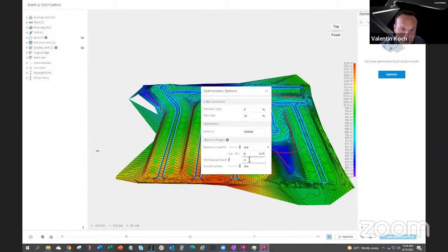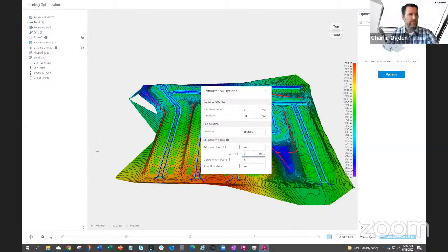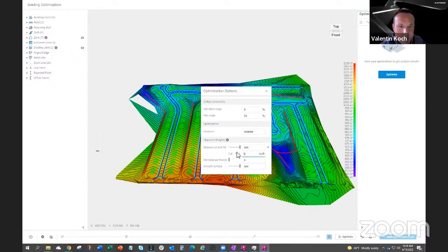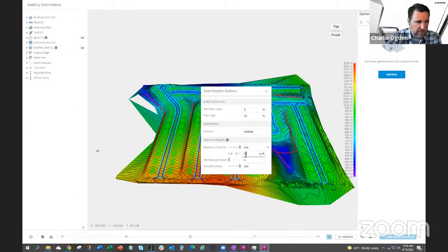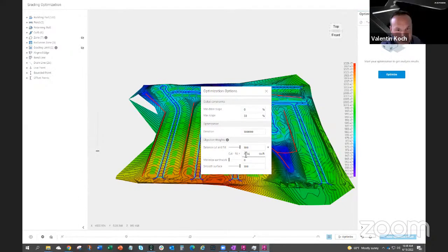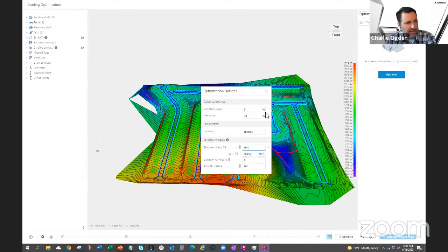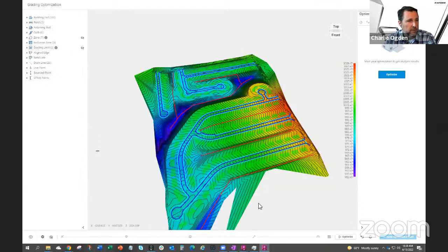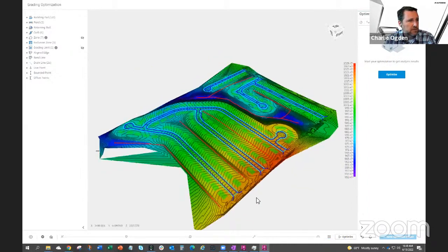So it was a fill. Is that right? Yeah, it was a fill. So we want a cut value. We want a positive one in here because this is cut minus fill, right? Yep. So what was the number again? 70,543. Perfect. So that'll adjust for the slight difference between the corridor and the original optimized surface.